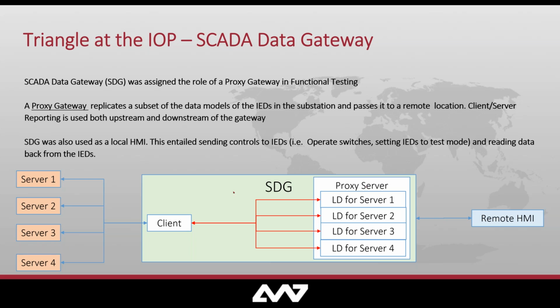We were also able to use SCG as kind of an ad hoc local HMI. By that I mean we could issue controls via the SCADA Data Gateway user interface. This is a product that runs on both Windows and Linux and has a browser-based UI. So you just log in and we could issue commands or controls down to the different IEDs to maybe operate switches, change an IED into test mode, and so on and so forth, and then read that data back into the gateway.